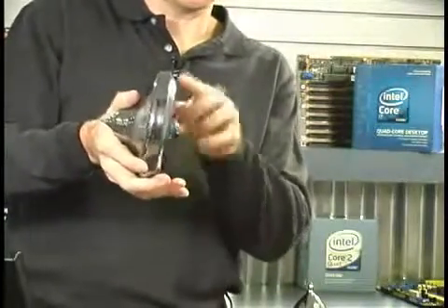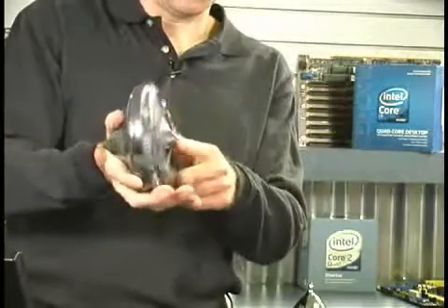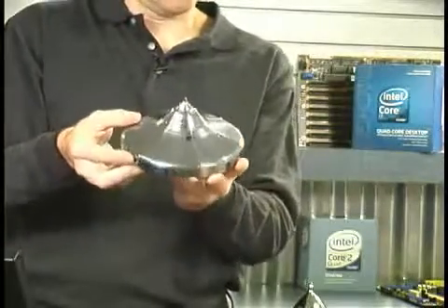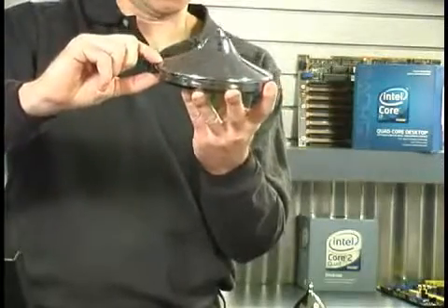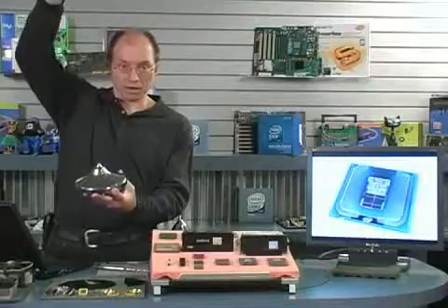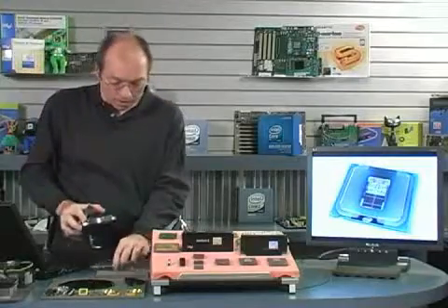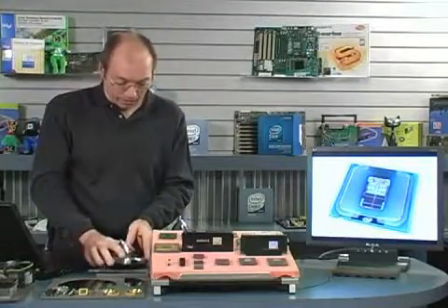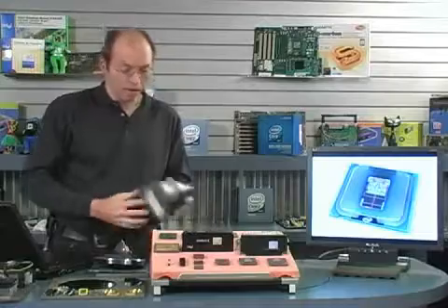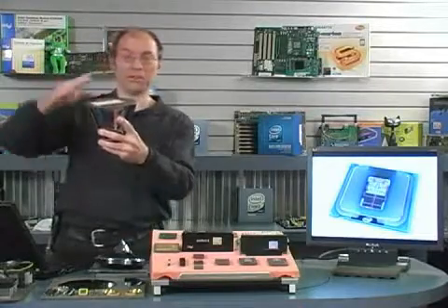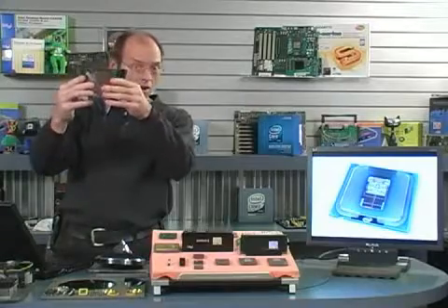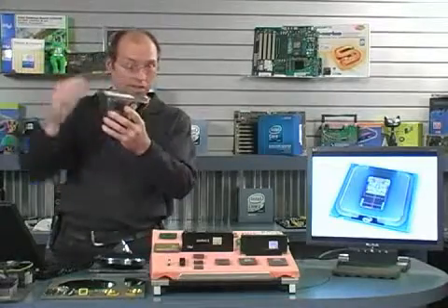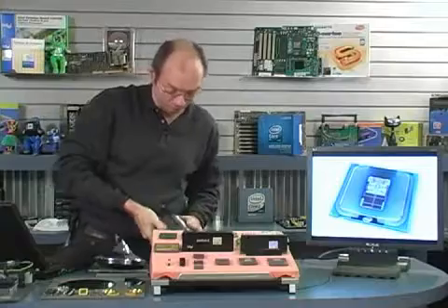Now, the tail on this crystal is very short. It's very short here, as you can see. In fact, this was an aborted crystal process. Normally, the main body would be not just an inch here, but would be several feet tall. This, in fact, is here as an example of a tail of a more complete crystal. So if you can imagine, this thing was several feet tall, and then this was the tail that's basically cut off and is considered waste. The head and the tail are then chopped off of this crystal.